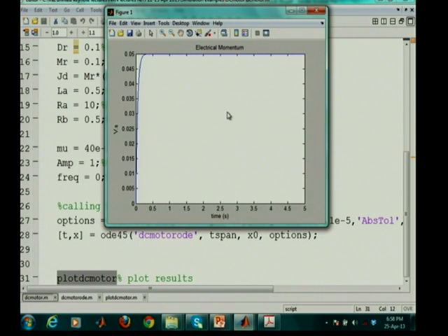So it's an adaptive Runge-Kutta, and that is why it could take more or less time depending upon the stiffness of your system, or the occurrence of transients or discontinuities in your system, or a few more factors.